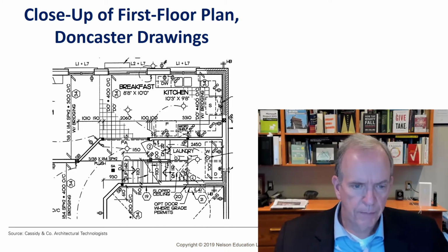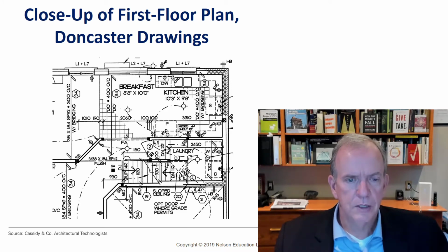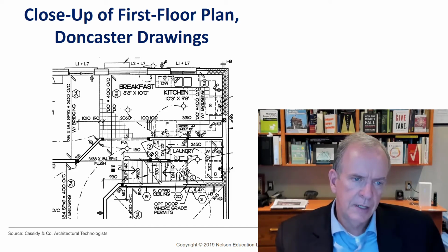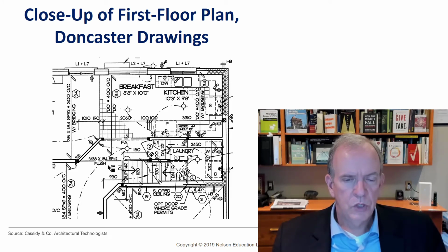So just giving you a little bit up on the drawing aspect, because it's hard to separate the two when you're teaching a course like this. So it's good for that to come together and get some understanding of what the drawings are saying and what we have to perform at. These drawings are in metric, so that's telling you 400 on center spacing. It's 300 on center spacing here. Depending on what you're doing and what's placed above, will change the spacing requirements for the joists.